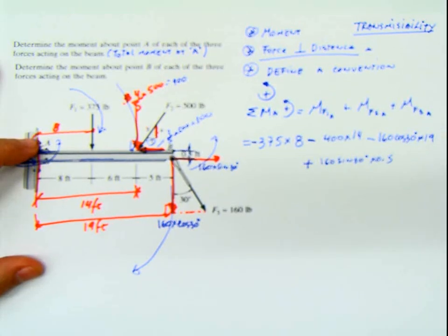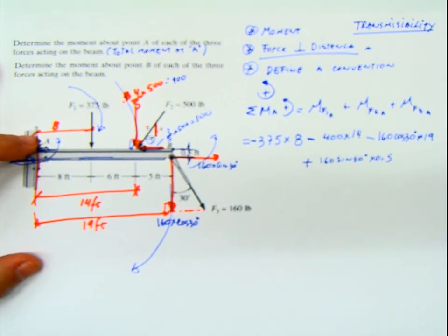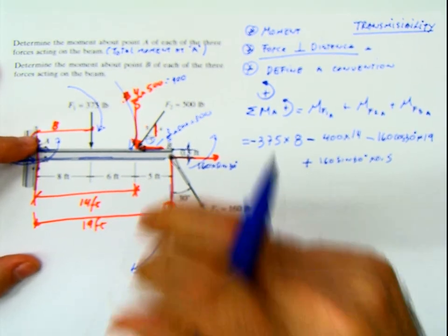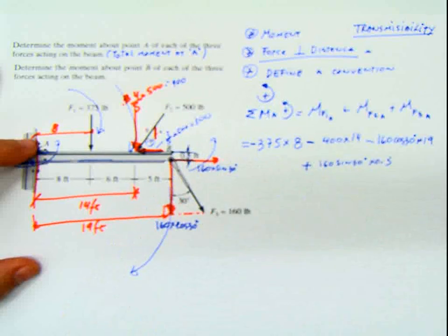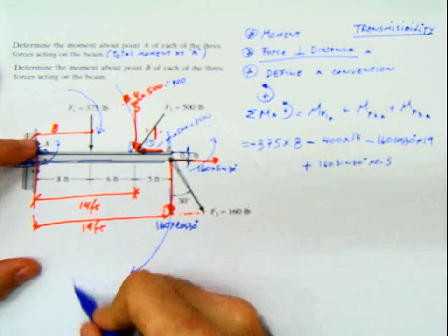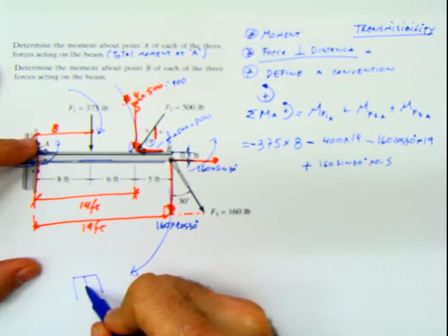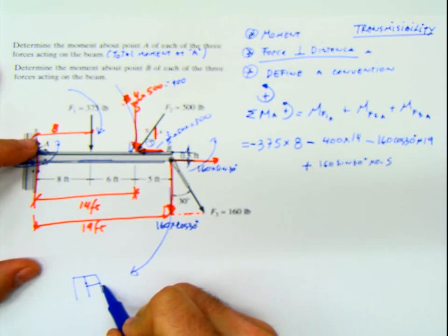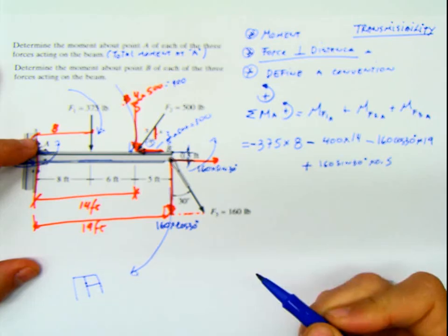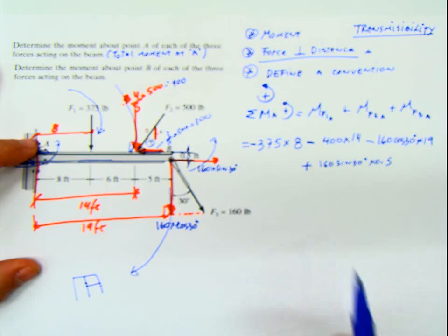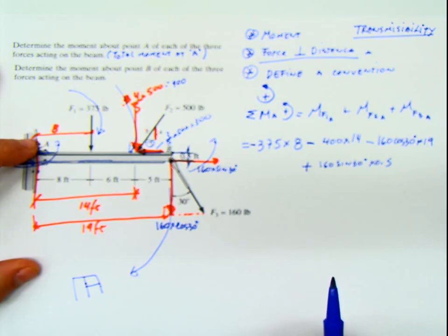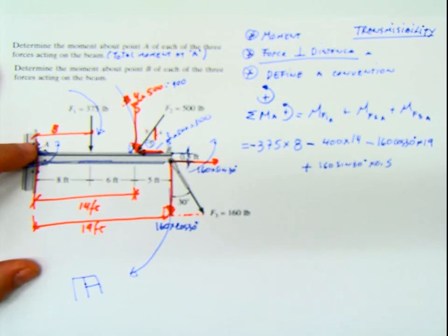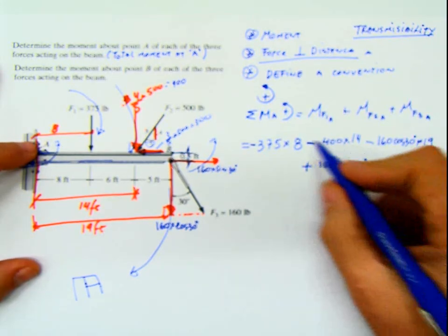That might take a little bit of time from you, and you might think that you know it perfectly. But when you have cases like this, with different legs, structures in this way, and you want to calculate the moment with respect to this point, or the force that happens here, here, here, everywhere around, you always are going to have to apply the principle of transmissibility. Even if you do it in your mind, you have to do it.